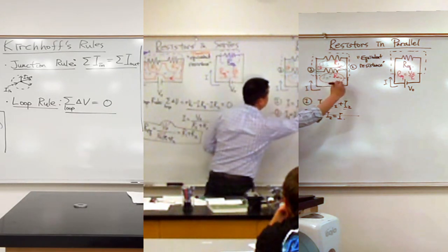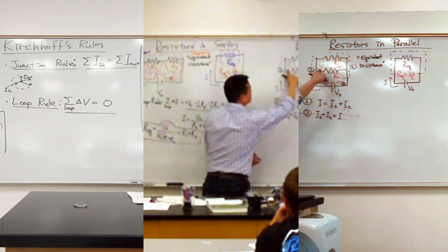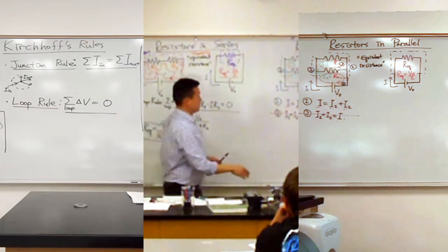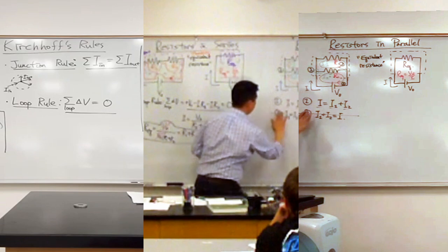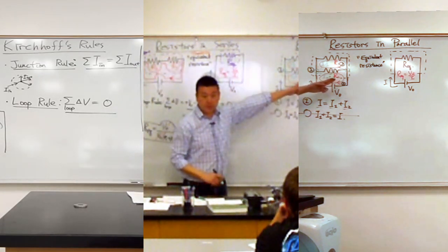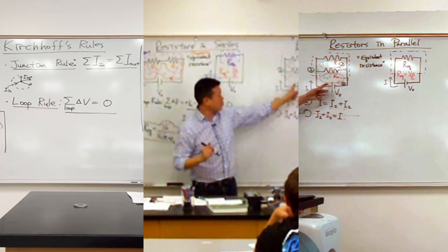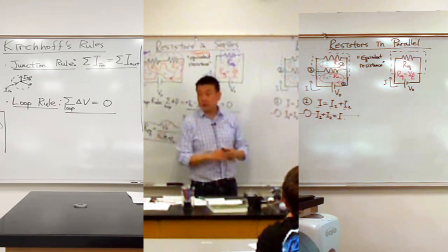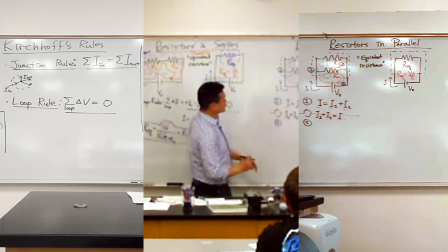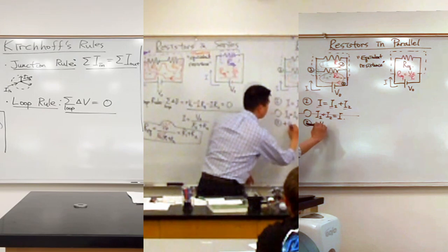Let me label this 2, because it'll be giving me equation 2. And let me label this loop 3, since it'll be giving me equation 3. And let me erase this other junction that I'm no longer using. All right. So my equation 2 comes from this loop. So I'm going to go through the same thing I did here before. I imagine starting from here, and as I go across each element, I figure out, all right, what is the change in the voltage? So for loop number 2, I'm going to first go over the battery. That's going to give me a voltage change of plus V0.